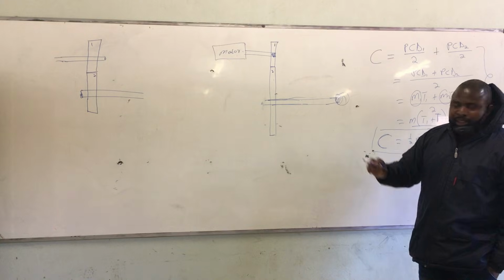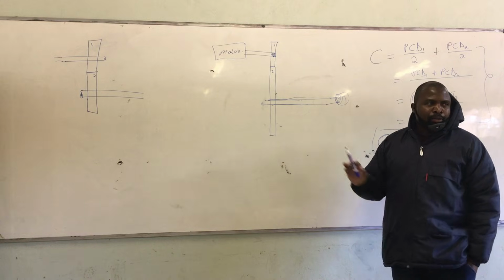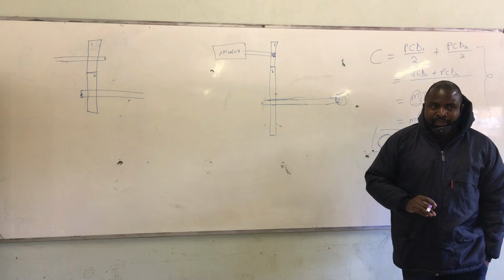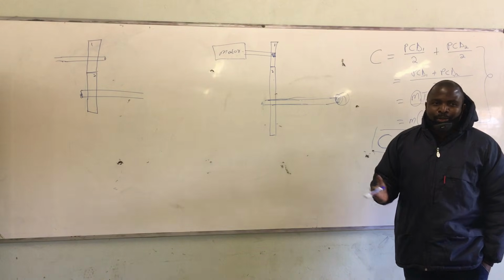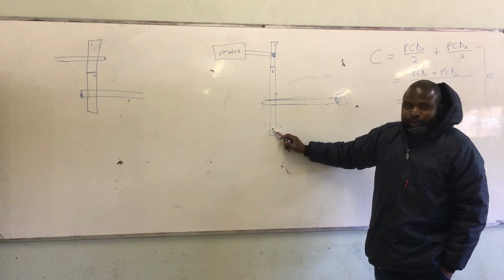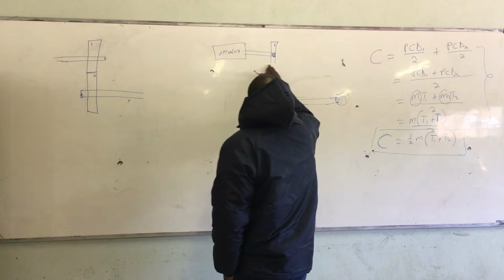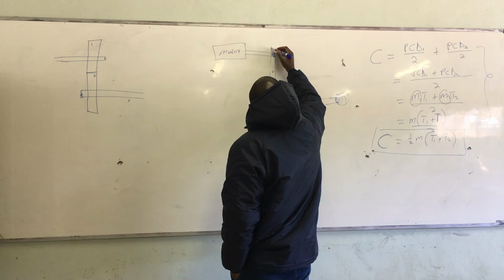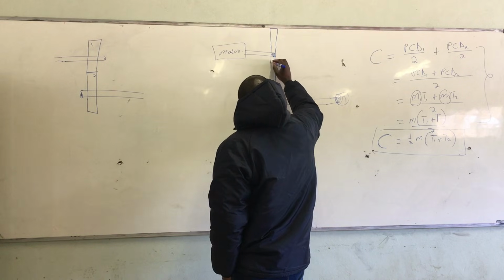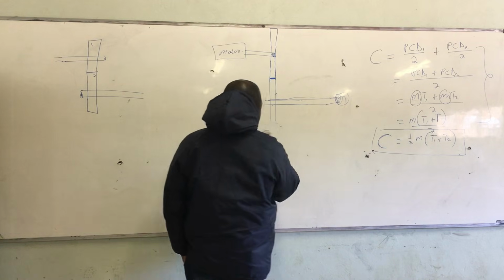As gear number 2 is connected to the wheels, let us check now. Is this car going to run or going to move slowly? It's going to move slowly, right? So we are saying this big gear is going to move slowly, and this one is going to move faster. Okay, now let us change our gears. Here we place the larger gear, and here we place the smaller gear.